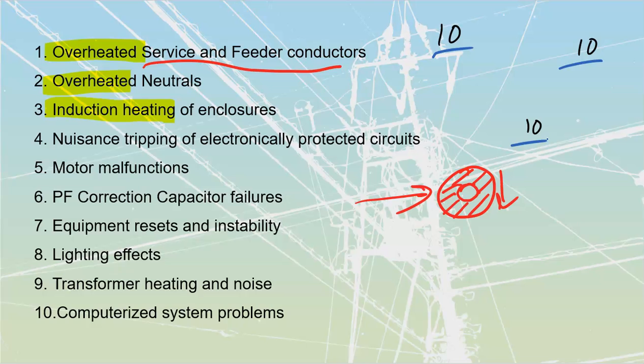As soon as these things start to add together, whether it's going to be completely, so that this would go up to 30 amps, or incompletely, it's going to be somewhere between my 10 to 30 amps, anywhere between the maximum of whichever one's going to be highest, in this case they're all the same, all the way up to the sum of all of those. And if we have undersized our neutral, which is what code allows us to do when we've got nonlinear loads, but we get these harmonics on there, all of a sudden we would end up with way too much current going through that system.